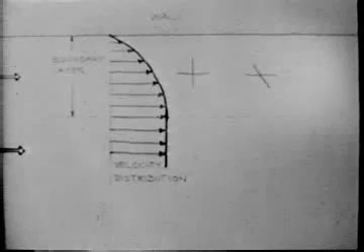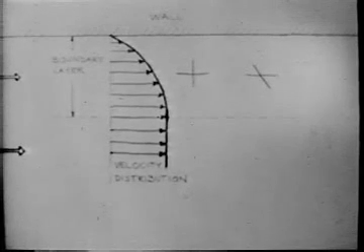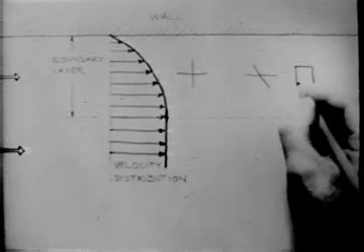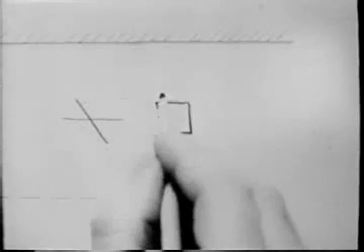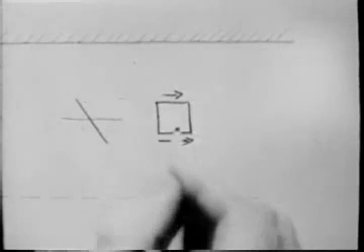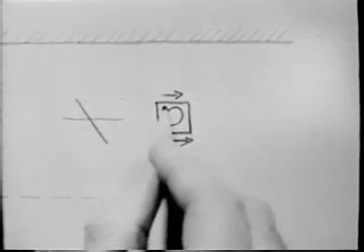Now let's look at the circulation for a small circuit in the straight boundary layer. Because of the distribution of speed, there is a net circulation, which is in fact related to the vorticity of the enclosed fluid. In cross-section, a single vortex line with non-vortical fluid outside appears as a point around which the fluid moves in concentric circles.